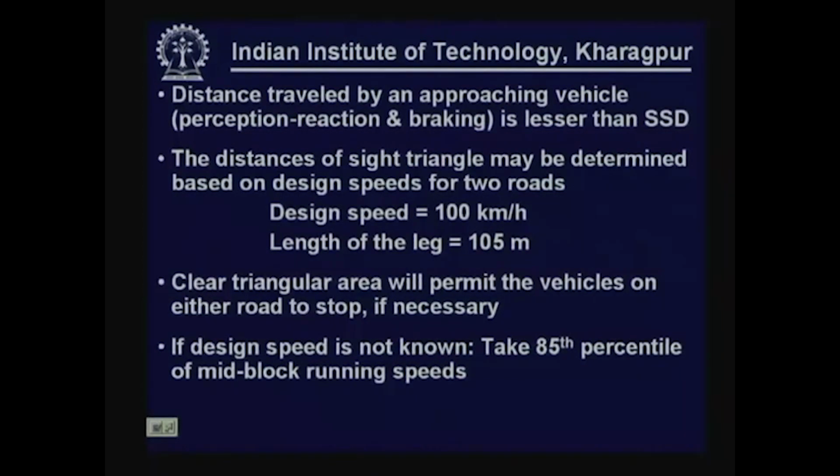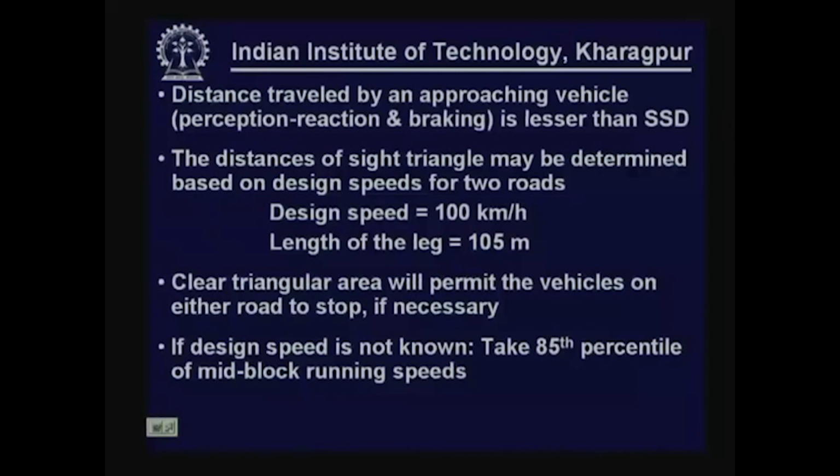Therefore, these values are normally lesser than the values for stopping sight distance. Based on field observations, AASHTO has suggested different lengths of leg as a function of the design speed. All those considerations are there.